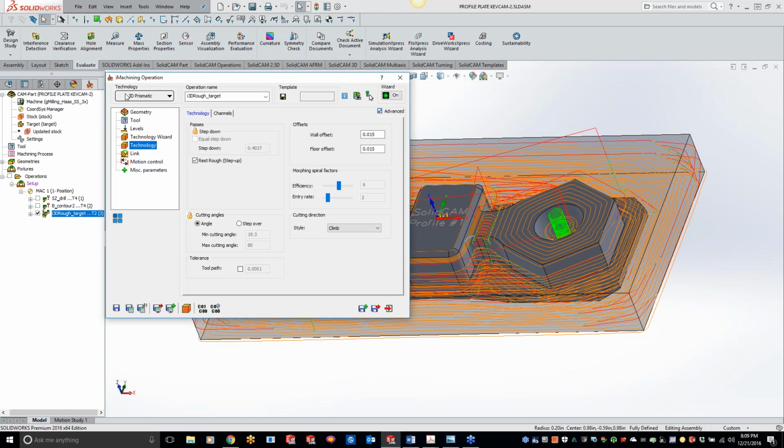I would say about 75% of 3D iMachining is going to be used for roughing. We'll go over one part where we can just do 3D iMachining and that's it, and we'll put these at 0. But it's all dependent on the finish you're looking for. This part, customers are going to see it, other customers are going to see it. It needs to be visually appealing, so we'll come back and lay down some nice paths. Right there, I've basically machined that whole entire part.